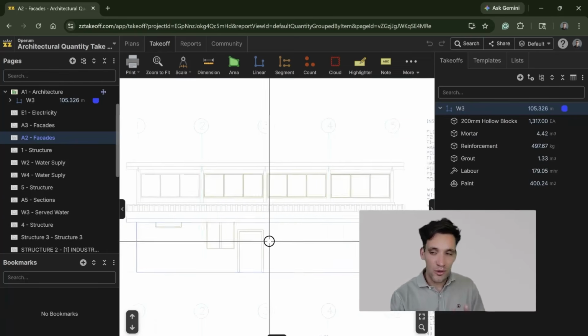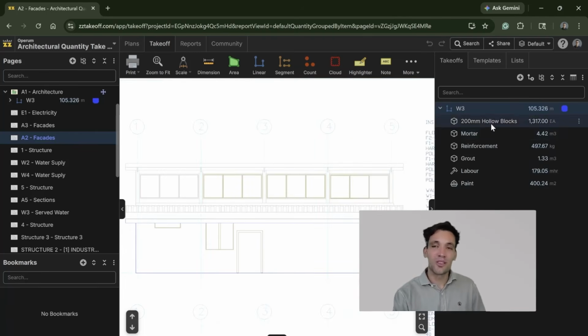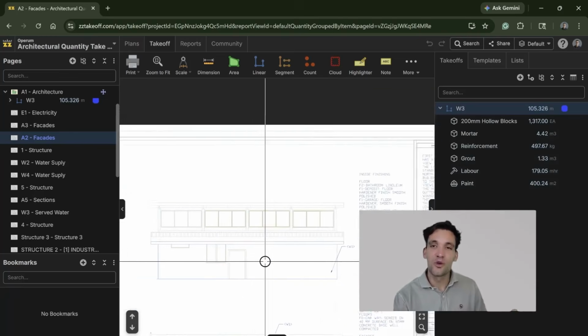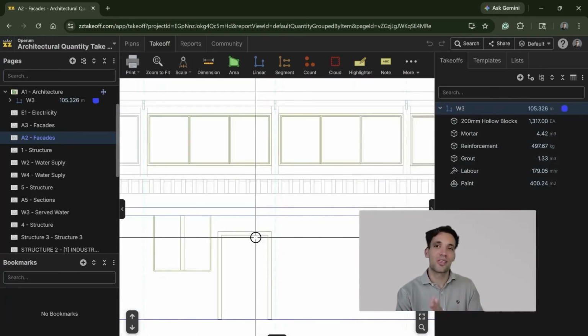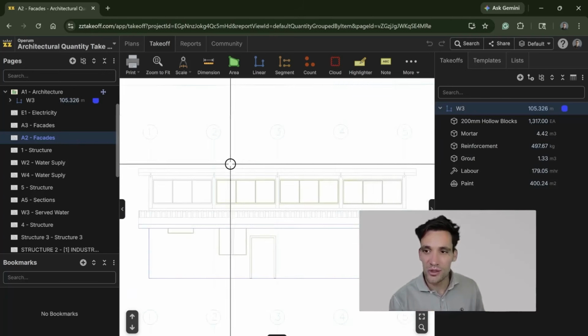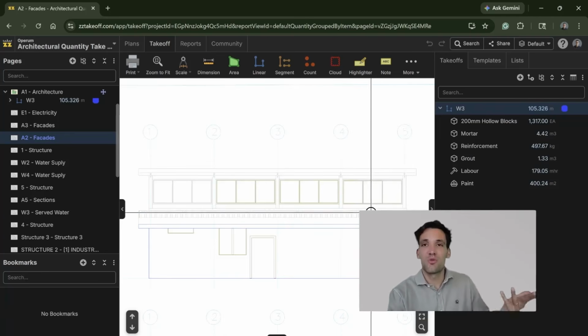So if I was doing this takeoff, I probably wouldn't even consider the doors as a double counting thing, because really you're including wastage, you're including all these other items. You could just choose to have a little bit less wastage. I think getting too precise with this stuff, you're almost going to have more errors and confuse yourself more. So I tend to not worry about that stuff unless you have a wall like this, which is literally all windows. So it wouldn't make sense to do a wall takeoff for that.